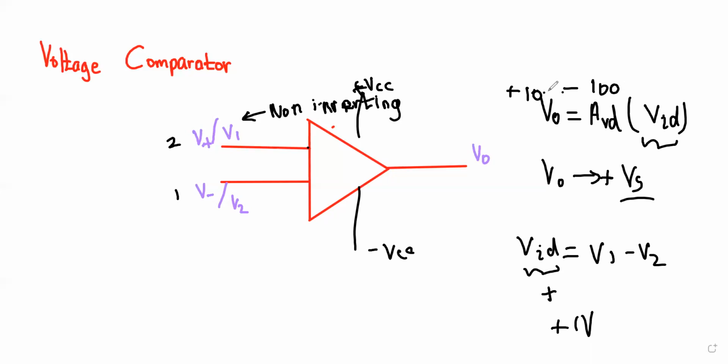But let's say we have only provided the plus Vs as, let's say, 3 volts. So the output voltage can only reach up to 3 volts. Even though theoretically we should get a gain giving 100 volts, we are going to get only 3 volts. So in this thing, you can directly mark it like this.